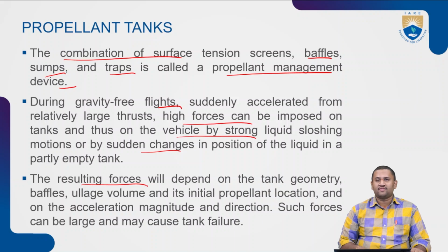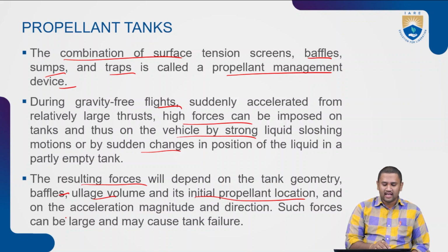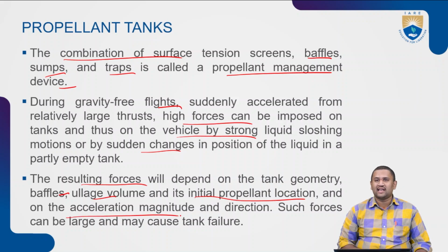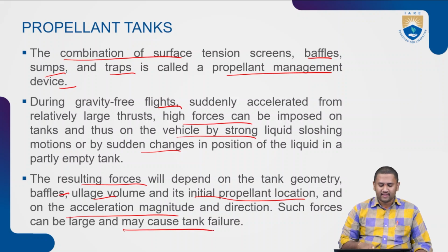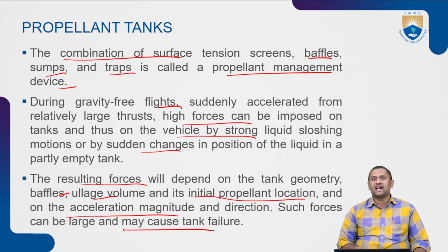The resulting forces will depend on the tank geometry, baffles, ullage volume as well as the initial propellant location, and on the acceleration, its magnitude as well as direction. Such forces can be large and may cause the tank to fail.